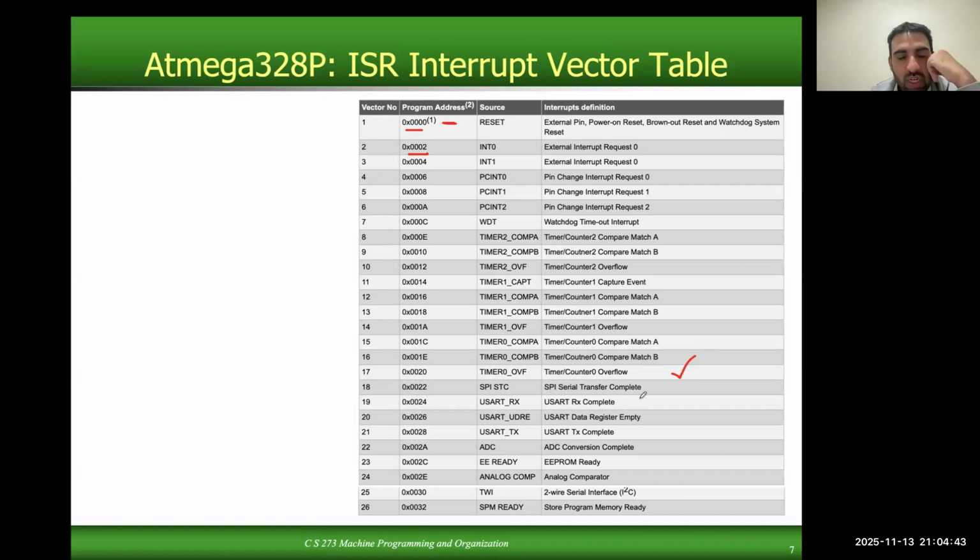So whenever an interrupt happens, which basically means whenever the overflow happens, we want our microcontroller to run the code which toggles the output. If it was 1, then it makes it 0, and next time when the overflow happens, it makes it 1 again, and so on. So we will have a square wave on the output then, right?